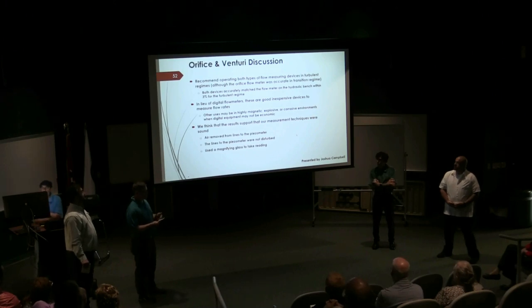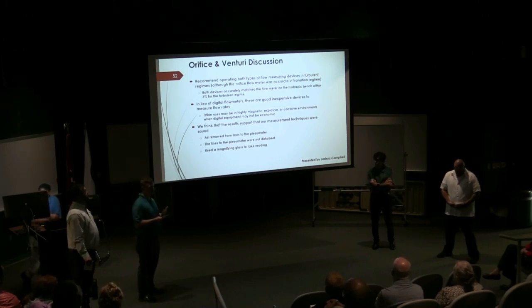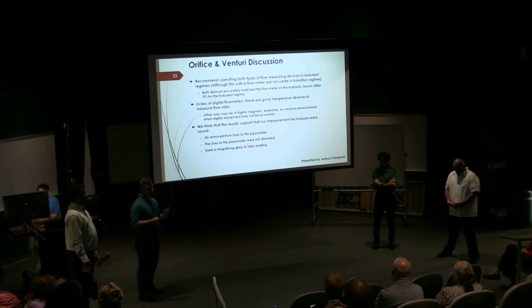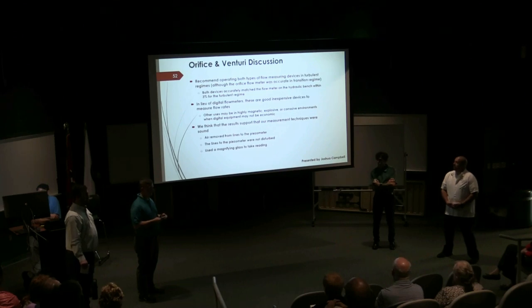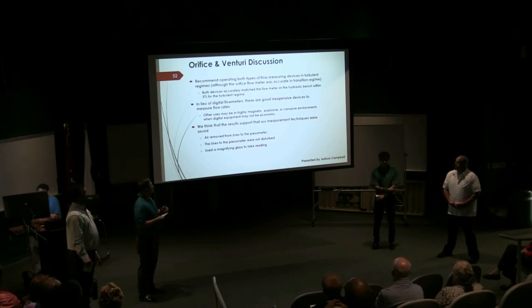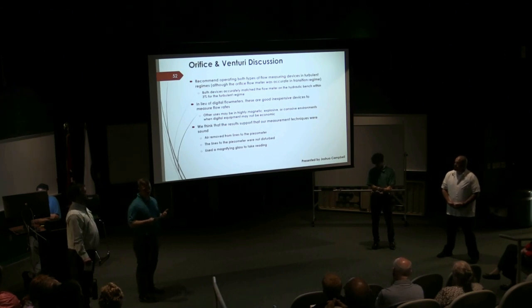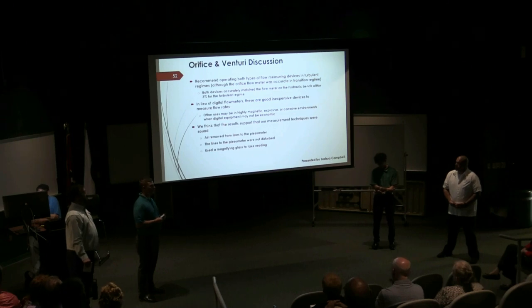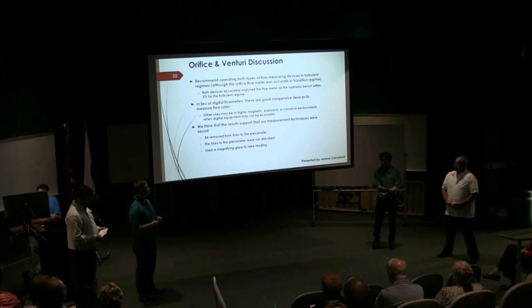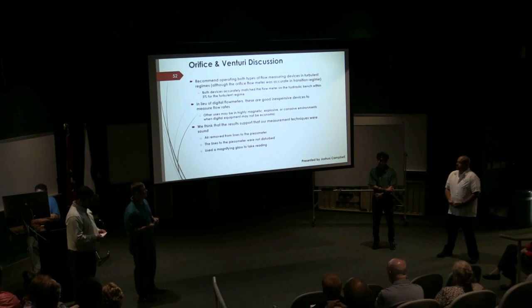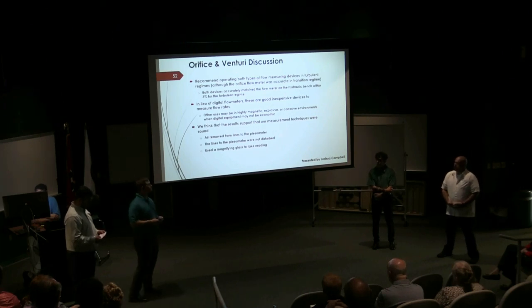Now, to summarize, although the orifice measured actually in transitional flow, we recommend operating both devices in turbulent flow, and we determined that these flow meters are good and inexpensive options. They can also work in many different hazardous areas that digital flow meters can't work in. And finally, we determined that our results support our measurement techniques.